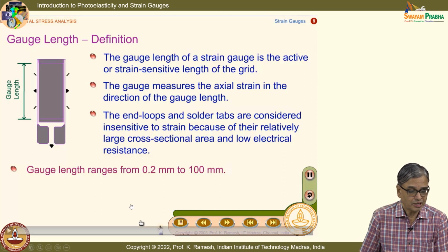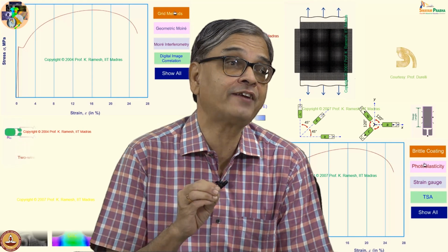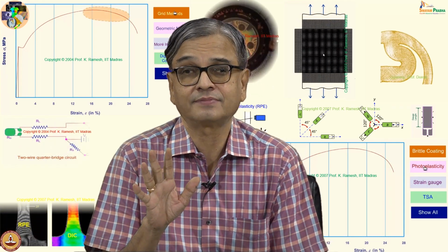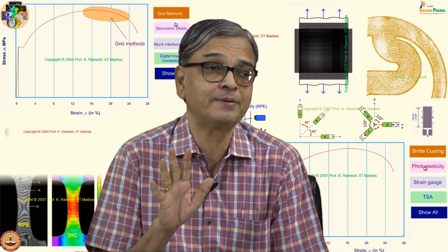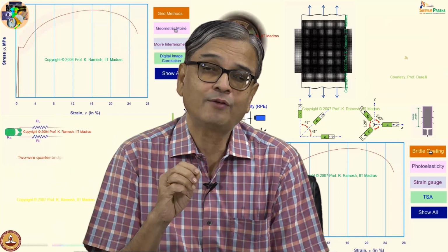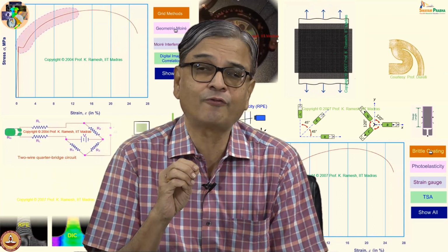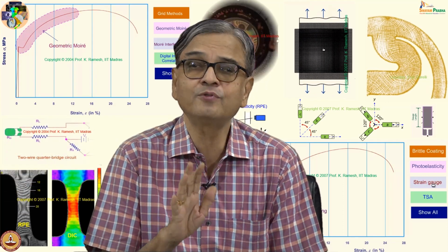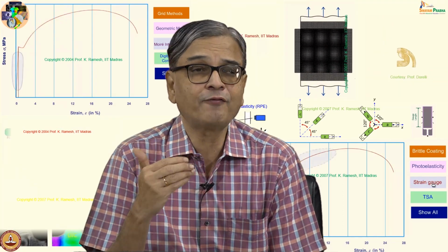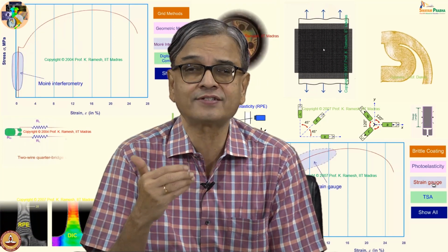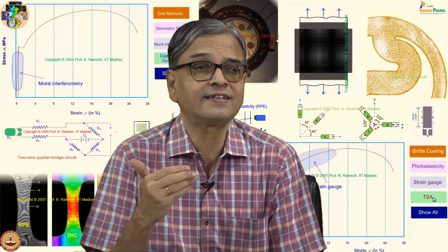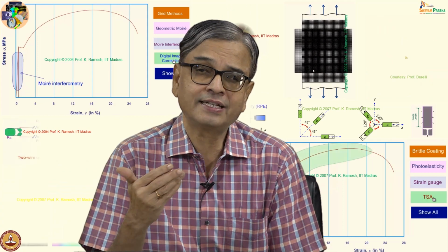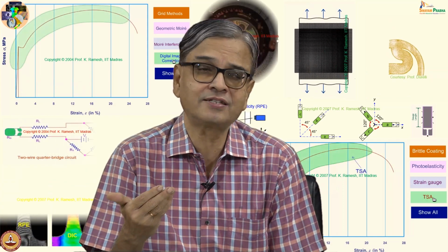So, you have to select what is the gauge length that is appropriate for your given application, and strain gauge selection is also a very important issue. And I want to caution, strain gauge is a widely used and abused technique. People abuse it because they do not have a formal introduction to what a strain gauge is, what are the sensibilities, because the electrical principle is very simple and straightforward.